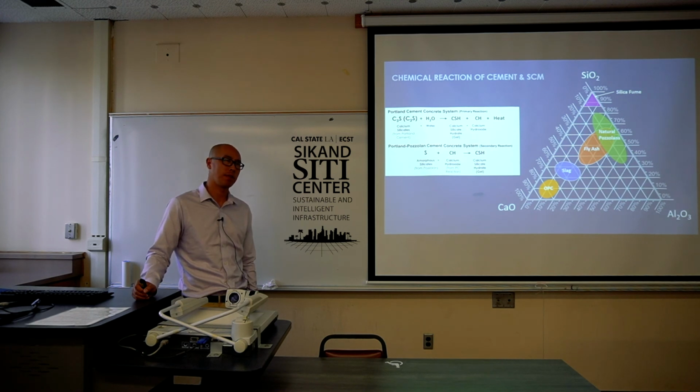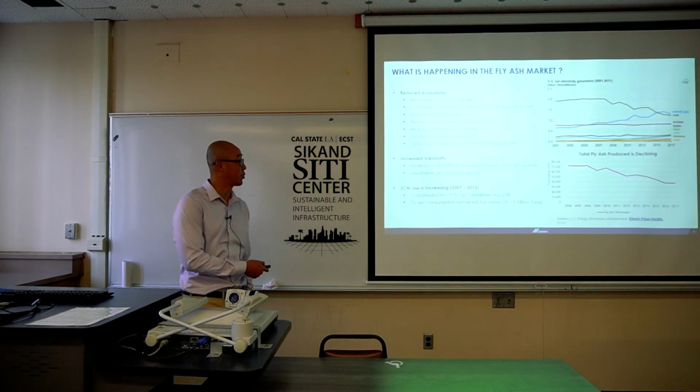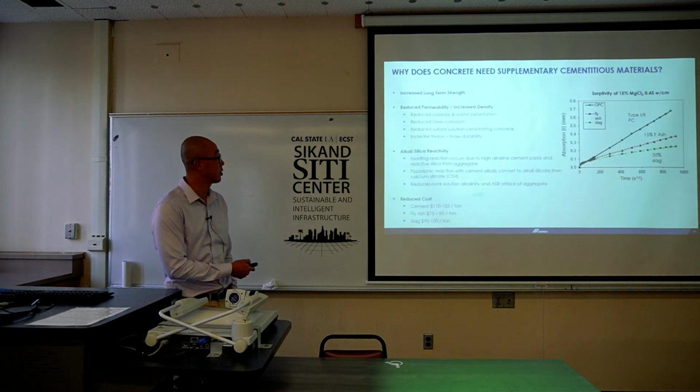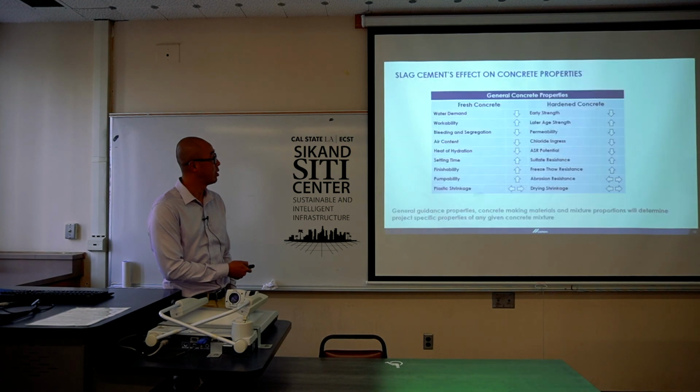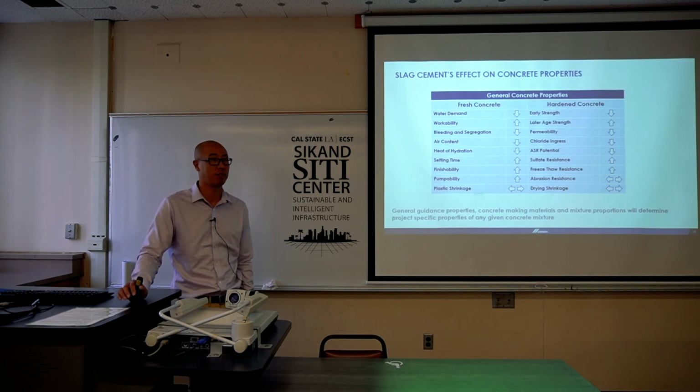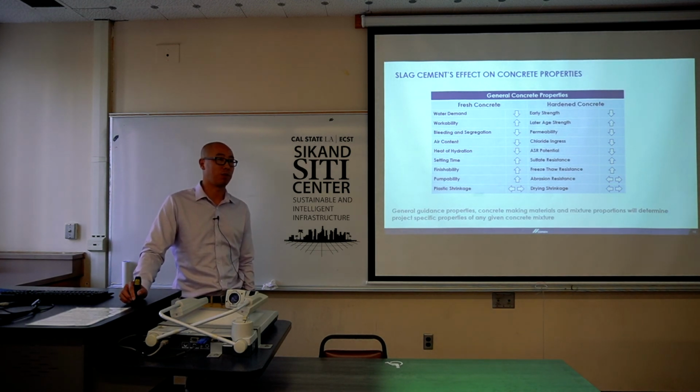Do you have any test results that show the effect of slag or fly ash on shrinkage or minor cracks or drying shrinkage cracks? We haven't done too much lab testing, but based on our experience, they don't have too much effect on the shrinkage. As I mentioned on the slide, for drying shrinkage, we usually think it's about even with conventional concrete. Not too much effect to reduce the shrinkage.